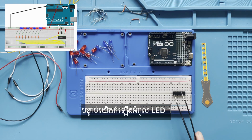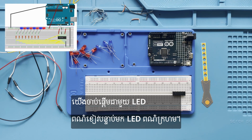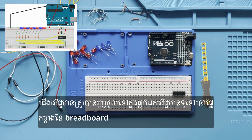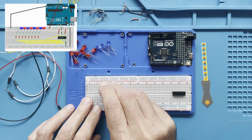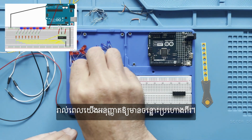Next, we install the LEDs. We start with a blue LED followed by a red LED. The negative legs are pushed into the common negative rail on the side of the breadboard. The positive sides go into the main section. Each time we allow for a space of 2 holes.